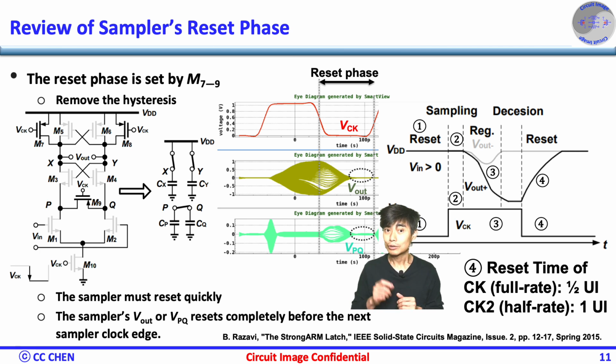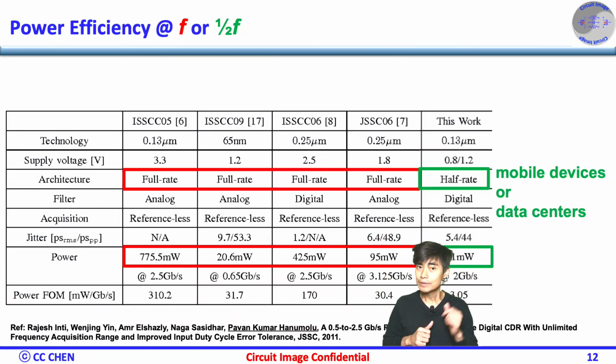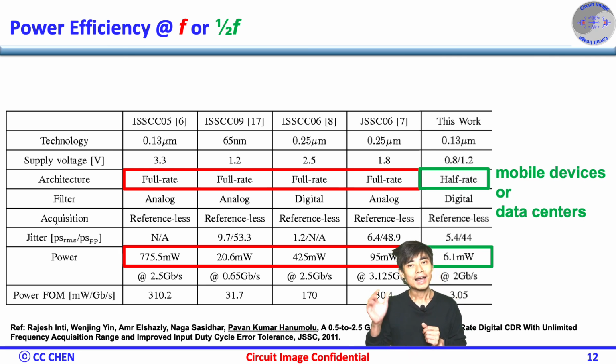Even if we are talking about the NRZ CDR, for any ADC-based digital CDR, the lower sampling rate at the front-end ADC would also reduce the DDJ compared to the full-rate sampling ADC. From the very beginning, we know the design complexity increases with high-speed clock frequency.